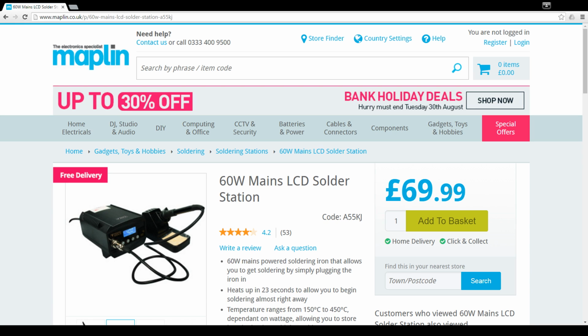Just a quick answer for the JHS open source about when and where to use capacitors and inductors. Capacitors tend to be used when you want varying voltage to become smoother. Typically with switches, you don't want them to bounce as much. You can put a capacitor in parallel between the negative or the 0 volts and the bottom of your switch, and it will smooth out any bounce that happens. Obviously it's not perfect, especially when you're using an Arduino, and there are more ways around that by using a 555 timer, but it does the job.